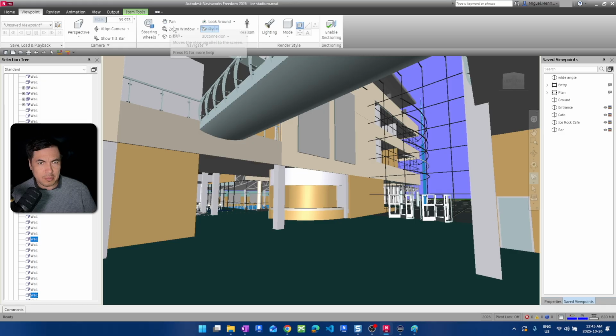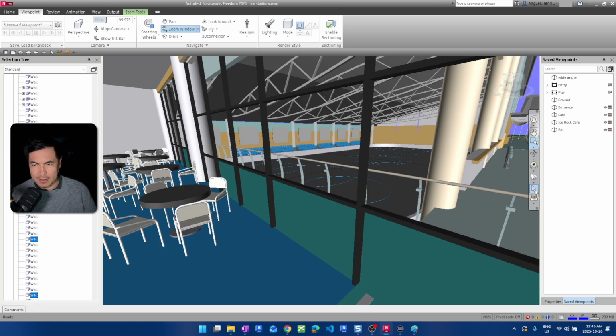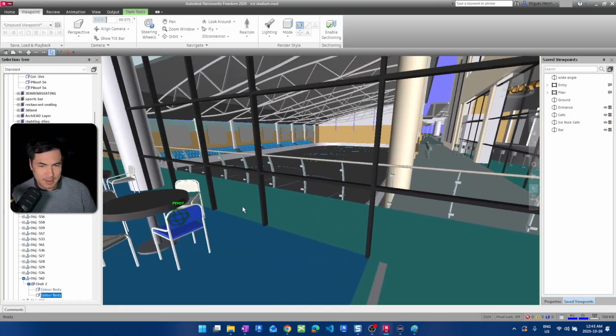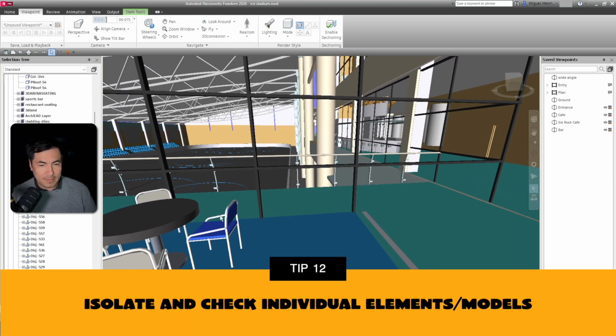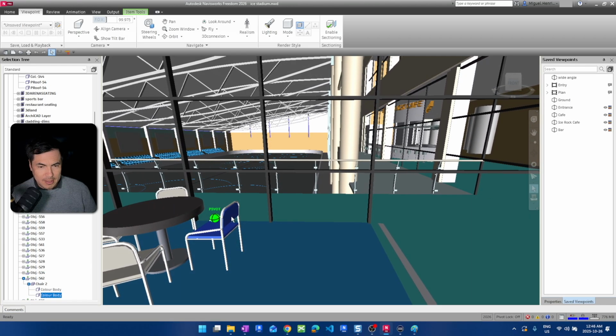And here you can also pan and zoom to window if you want to. And if you want to select things, you press on this icon and you can select something and pivot around that element. You can also, for example, if I want to select all these elements, press the spacebar and then drag to select the entire chair.